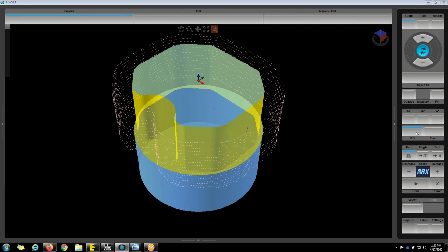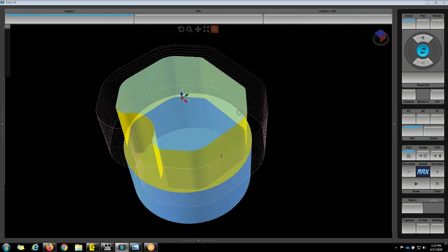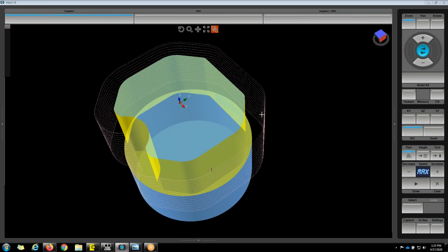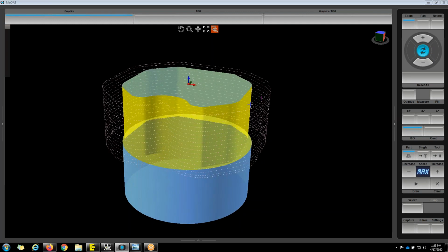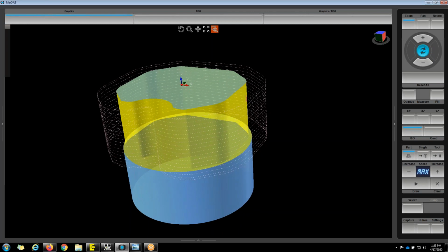What this is going to allow us to do is to create a ramp style tool path. Back before we had the swept surface option, there were a lot of times where I started creating a part where I really wanted to do the ramp style tool path on an odd shape, something like we have here. And I essentially just ended up going to a CAM system because I really wanted to do that ramp style. I'm a big fan of that style of cut.